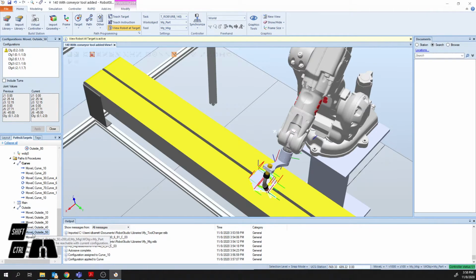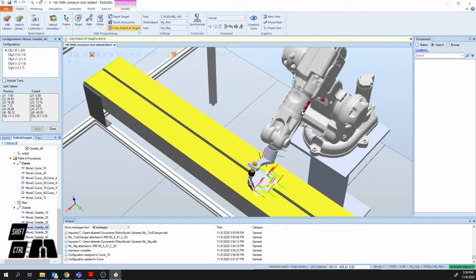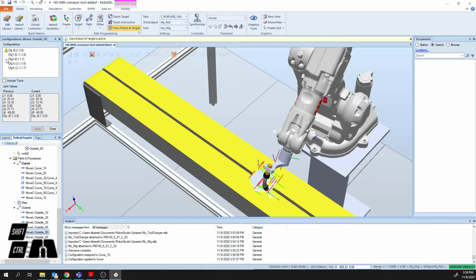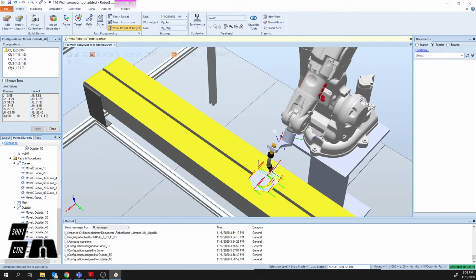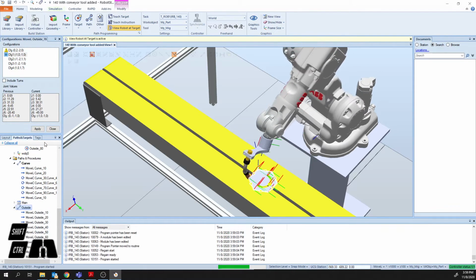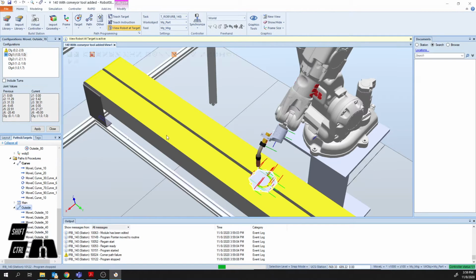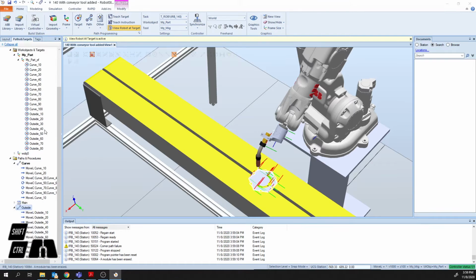Oh, right there, that point, number 50. Notice our tool, or the joint 4, between 40 and 50 has changed. So let's flip that over so joint 4 is the right orientation in 50. Let's move to 60, we have to do the same. And 70, we have to do the same too. And now let's move along path. That looks way better. So now, let's close this.